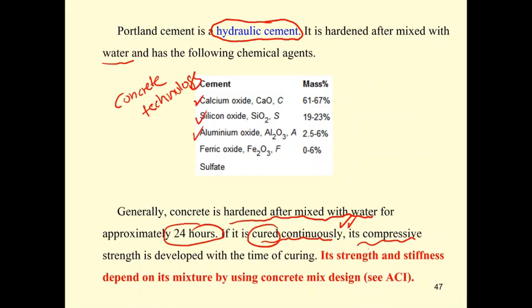So if you cure it properly, the strength and stiffness of the concrete will increase with time, even years after you finish the construction. But by the way, the concrete must follow the mix design.